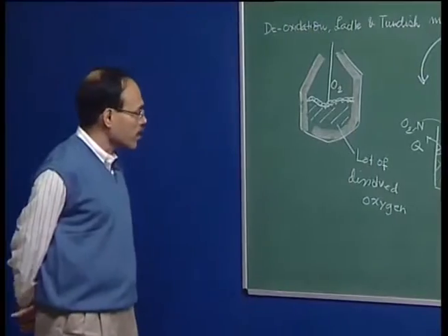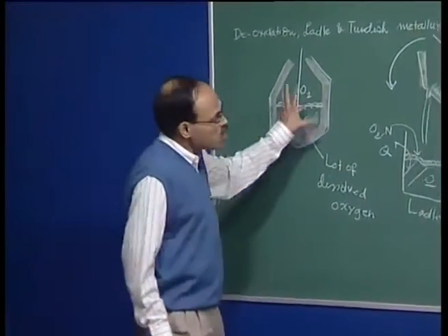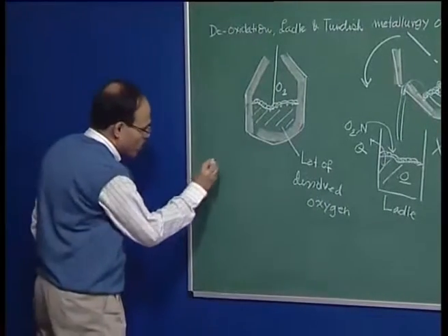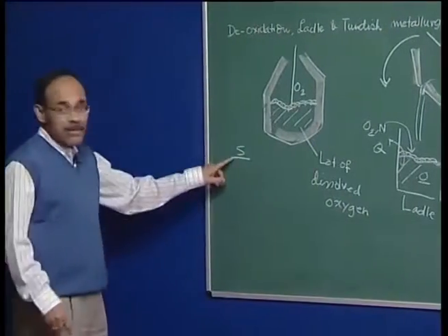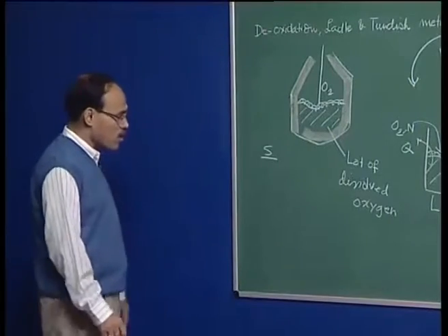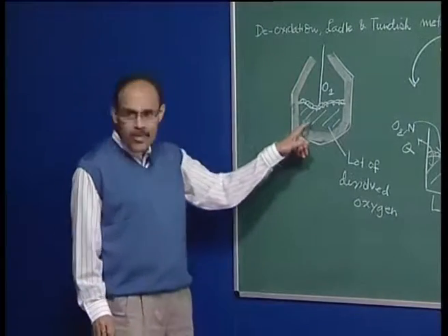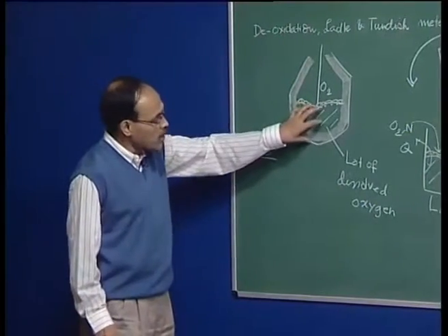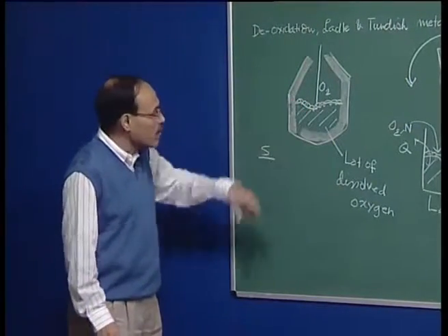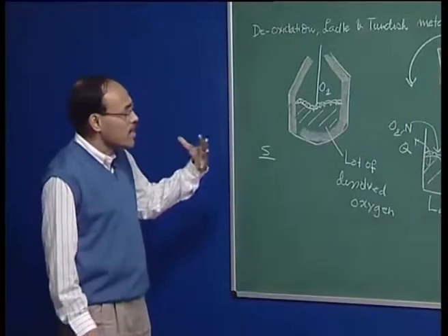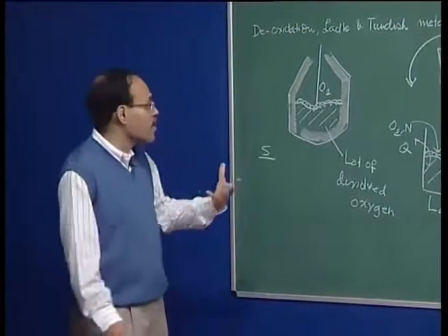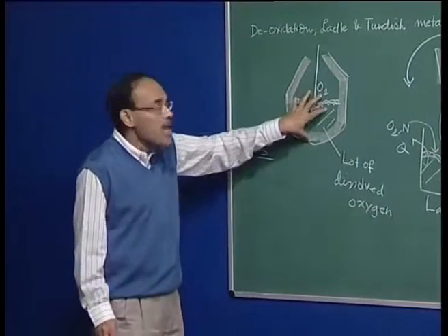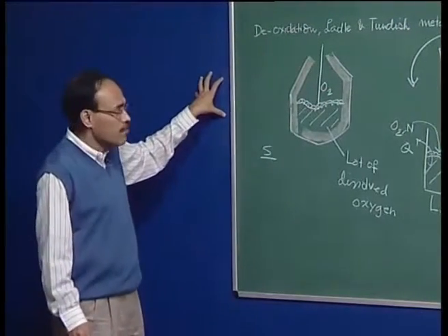amount of superheat. So, as primary steel making is over, we can assume that there is going to be maybe sulfur, which is more than the required specification. Although we would like to have phosphorus absolutely in the right level, I must also mention here that there is an increasing trend that for high phosphorus steel we are going to have some kind of a pre-treatment, which you of course have done.